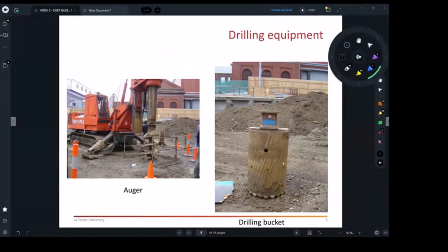Yeah, so we use these guys to actually go through that fill, sandy material, and then make a 1 meter diameter hole, right? And then we can prop it. We can prop that hole. So basically the buckets, they go down and then we excavate at the top. The bucket is going to go down and excavate, so they act as an excavator. They're going to be excavated into the ground, and you're going to pull out the soil.